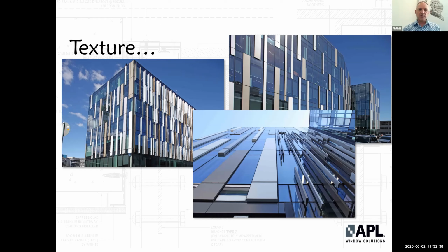So it's not just the architect drawing what they think looks good. There is a science behind it as well. You're probably looking at a percentile of shading on the facade to achieve a certain shading coefficient, and ultimately that reduces the load on the building management system.